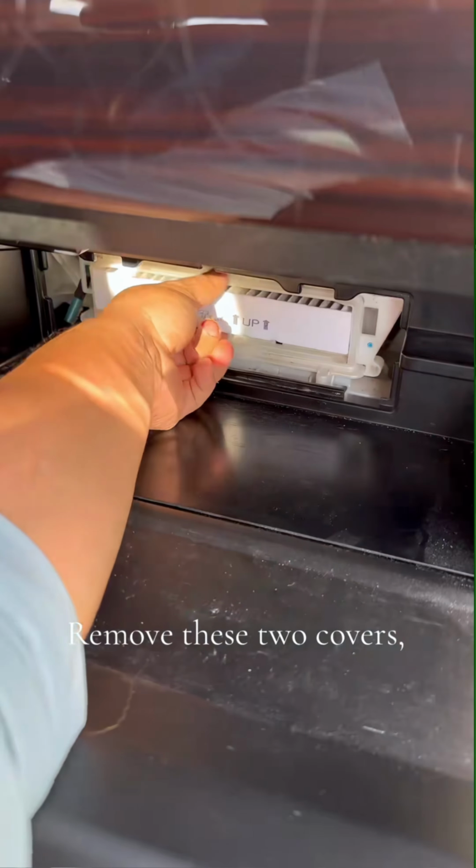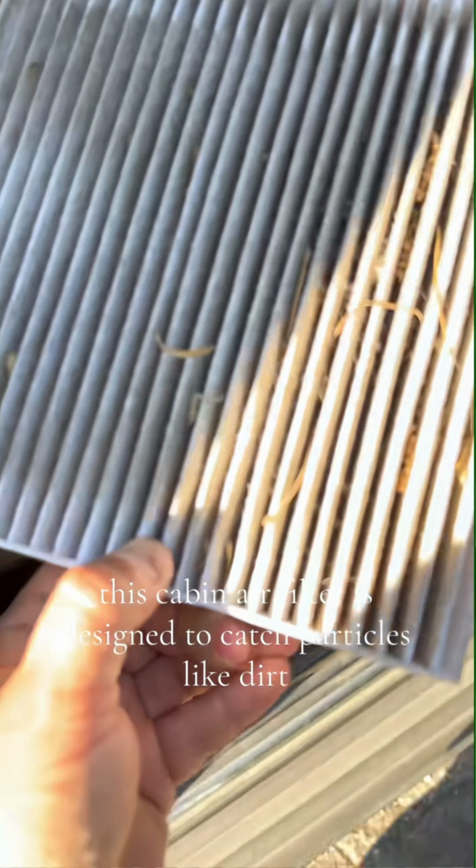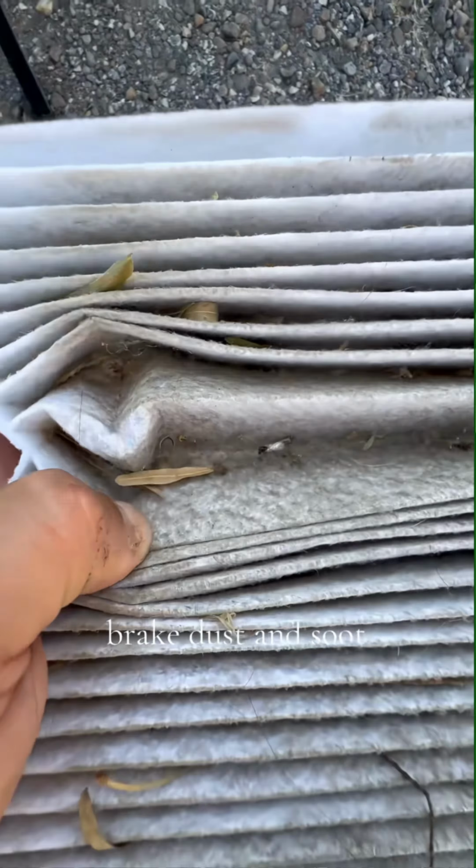Just remove these two covers, remove the air filter. Notice how dirty this one was. No wonder this truck had AC problems. This cabin air filter is designed to catch particles like dirt, brake dust, and soot, and obviously grass and leaves like in this case. So make sure you're checking and changing your cabin air filter at the manufacturer's recommended service interval. Filter that I'll be installing is a Purolator One cabin air filter.